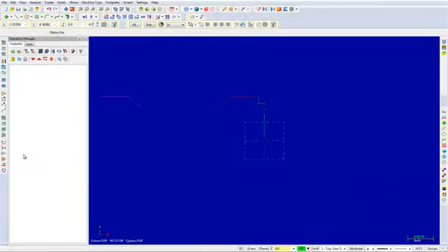From here, select the Clear Colors icon to return the geometry back to its original form. We will now create the final lines to finish the outside profile. Select the Create Line Endpoint command to complete the geometry. Pick the two endpoints as shown to create a line between the geometry and press the Apply button.